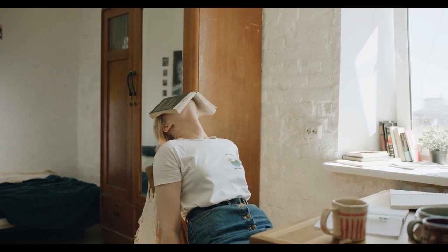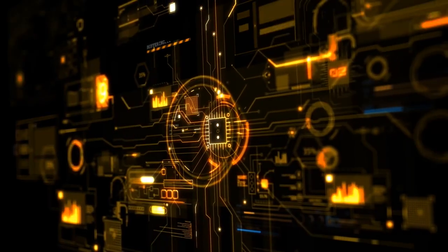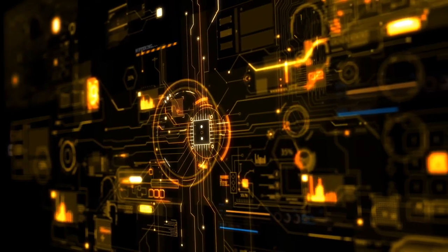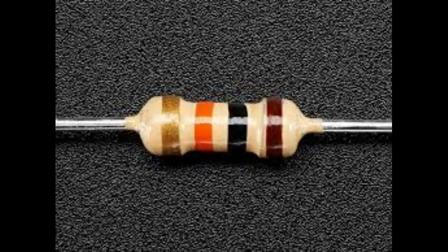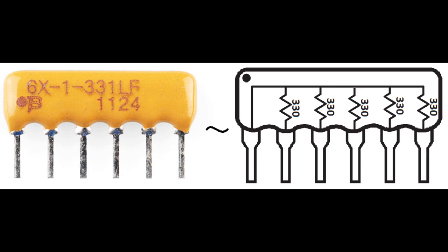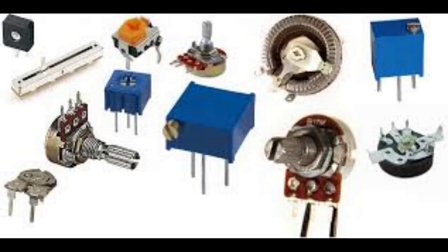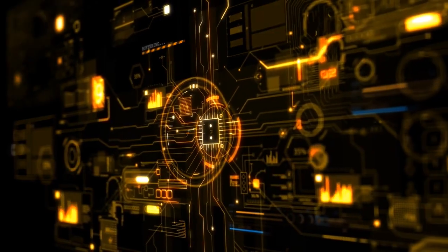Don't worry about all that mumbo-jumbo for now, but it's important to identify resistors in circuit diagrams, PCB boards, and service manuals. Resistors are typically symbolized as a zigzag or square-shaped sign with its value denoted on top of the symbol. Resistors come in either through-hole technology or surface mount package types, static non-changing, or special variable resistors. Static non-changing resistors can be identified by a standardized color code.